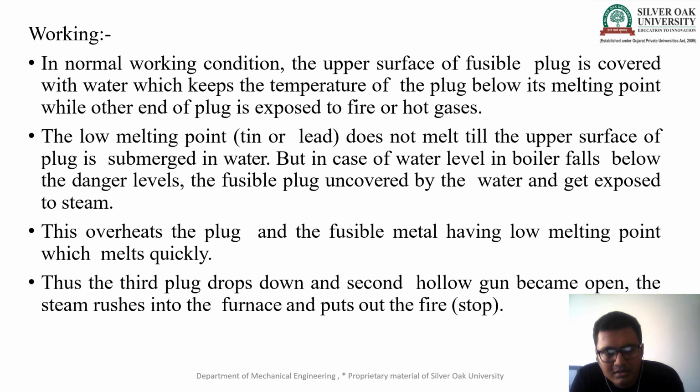The temperature of the steam is high, so due to the overheat, the plug and the fusible matter, having a low melting point, melt quickly. Both the gun metal pieces melt. The third plug drops down and the second hollow gun metal piece opens, and the steam rushes out into the combustion chamber or furnace, and the combustion stops, putting out the fire.